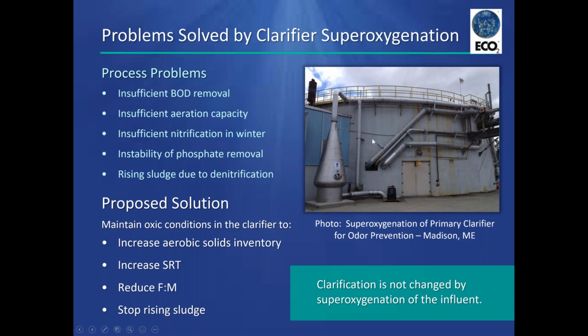The other alternative is to prevent the odor from forming in the primary clarifier altogether, by keeping the oxygen content in that clarifier positive, so that no hydrogen sulfide is able to be formed.